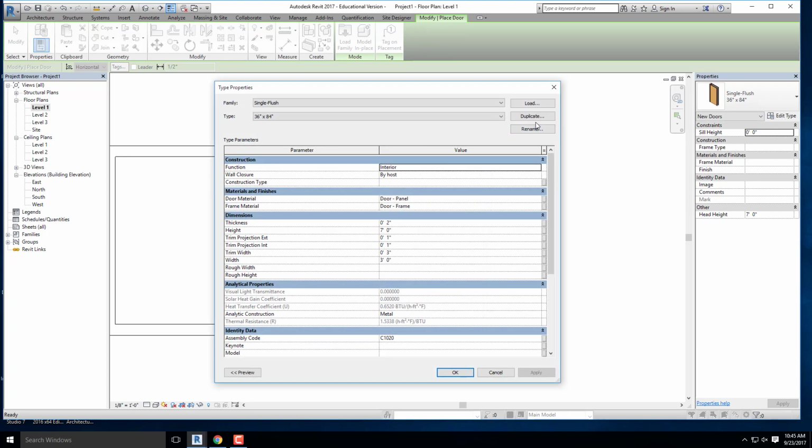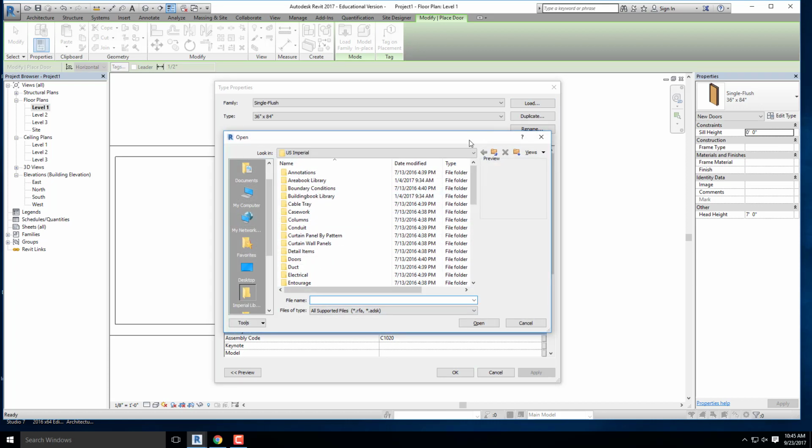And then what are we going to click on? Load. Correct. So we're going to click on load. Then doors. So we're going to go to our door categories. If you were looking for a window, which you'll have to do for this exercise too, you would click on windows. Then you can go through and select the window that you want. So we're going to click on doors, and then we're going to click on what? Residential, exactly. So you could select from these options right here.